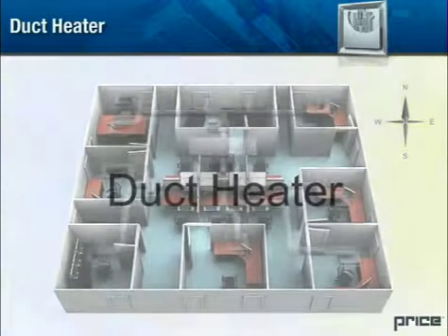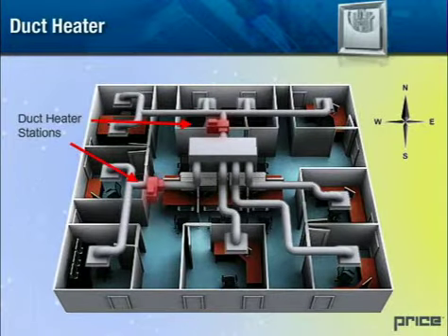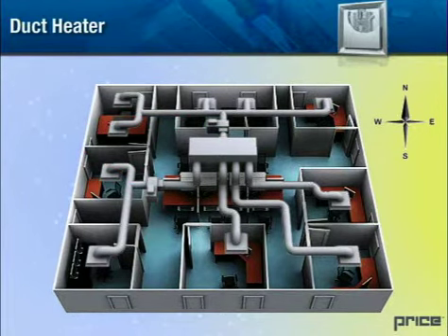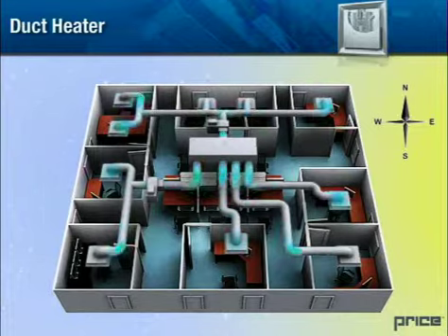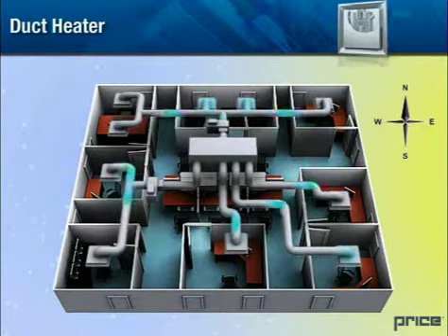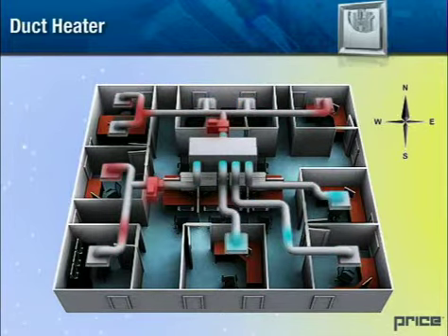Duct heater. Duct heater stations, an alternative to perimeter radiation or radiant panels, allow for thermal and ventilation demands in a large multiple demand zone system. For zones that require heating, instead of all the VAV diffusers closing when the air handling unit increases the supply air temperature and the room temperature increases, specific duct heater stations can energize to supply heat to the specific zones.